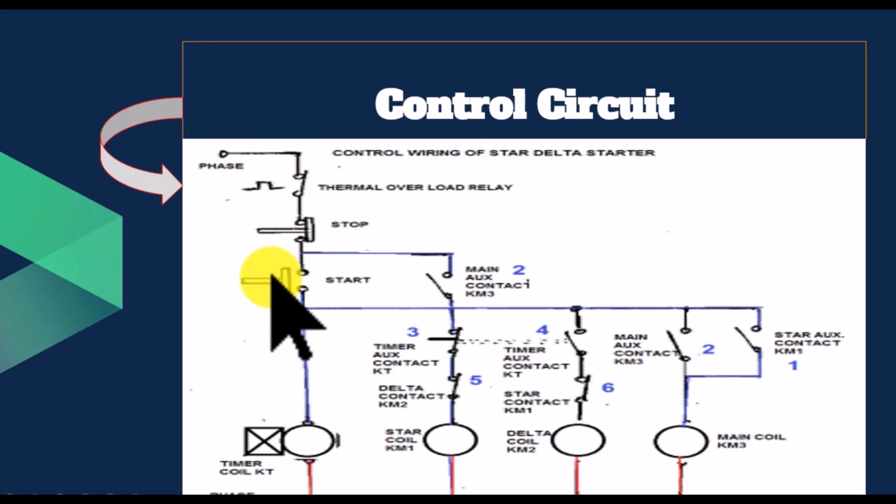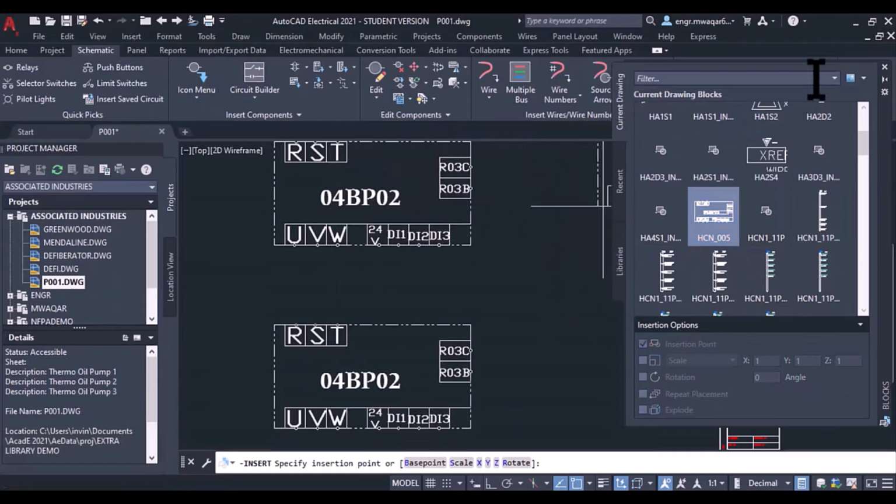And the logic side. That's the control circuit. These circuits use really low current to tell the high voltage circuits what to do. They're the brain. The nerves. They deal with things like contacts, relay coils, push buttons. So understanding the difference between the muscle and the nerve is fundamental to reading the whole system. You can't understand the drawing without it.